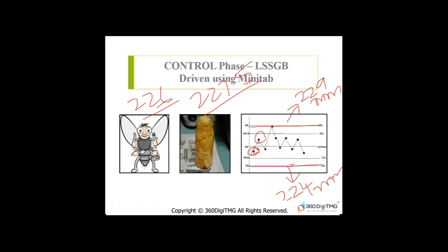Then you plot another point on this control chart. Say the next cricket ball that you have manufactured, say the circumference of that was 226.5. You plot the third data point. So on and so forth, as you manufacture the ICC cricket ball, as you get the circumference of that, you jot it down on the control chart and record it.